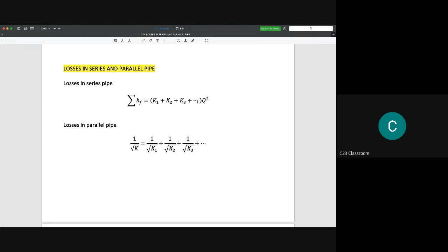The changes of velocity do not change the friction condition anymore. So a few researchers tend to assume that all of those parameters, the F, the L, the V, and so on, are actually constant. That's why we have a symbol of K here in calculating the losses. I hope you could refer to our last meeting to derive or prove this equation.